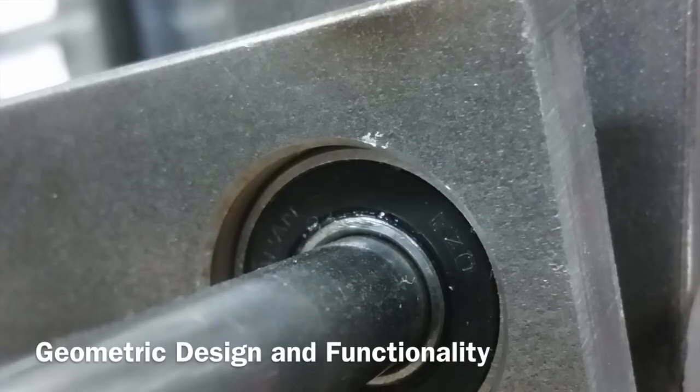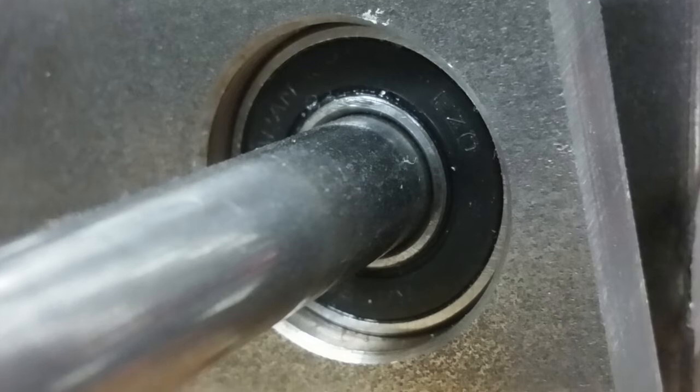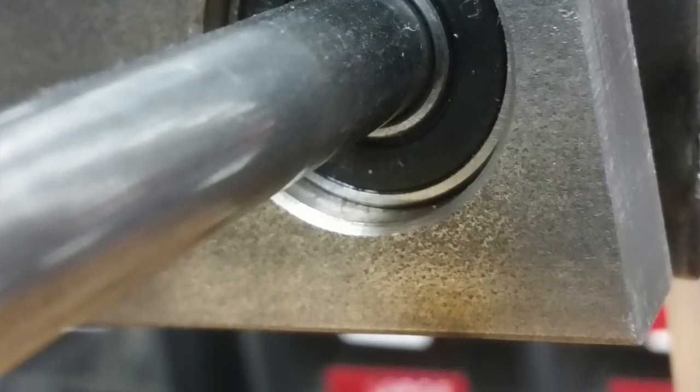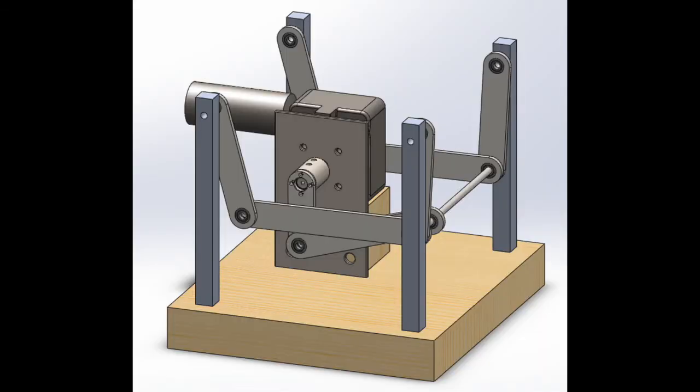The biggest geometric design challenge was designing a way to mount the mechanism in space so that it be firmly planted to a ground plane and yet still allow for full range of motion. Early designs accomplished this, but proved too hard to construct with given equipment. Another challenge lay in reducing friction during motion. This was solved by using press fit bearings at pivot points and brass washers between each link. Pictured is the final project design that minimized friction while allowing for full range of motion. It also allows for a full-size chair to be mounted as desired.